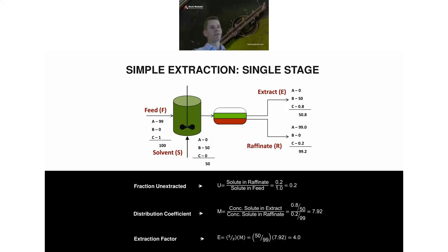raffinate phase. The extract phase essentially is a solvent that has hopefully a large fraction of that solute you're trying to extract, or the contaminant you're trying to extract. And the raffinate is essentially the leftover feed stream that has most of that solute or contaminant removed.